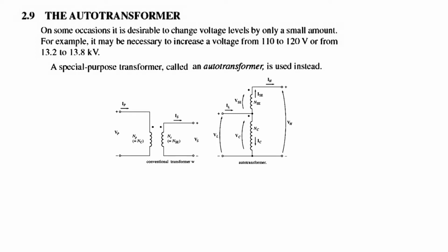And a couple of things related to the autotransformer: this configuration is what is called a voltage up transformer, where the input is increased, or a step up transformer, but this configuration is a step down configuration. Same thing, we are now taking the output from here and the input is connected here. So these are the two configurations.